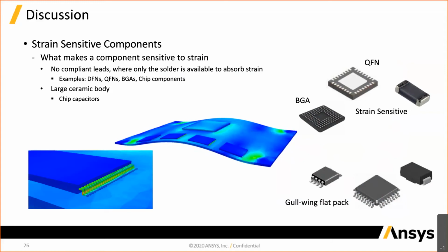You don't get that spring without a lead frame. So you just got to be careful with these strain-sensitive parts, your QFNs, your BGAs, your ceramic chip capacitors, and that type of stuff.